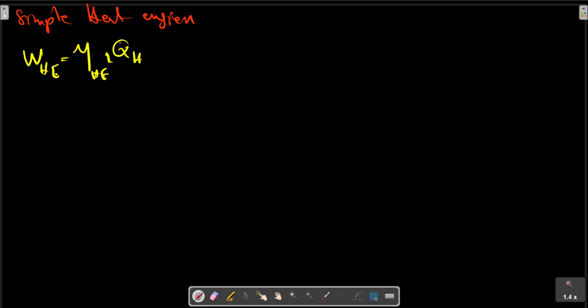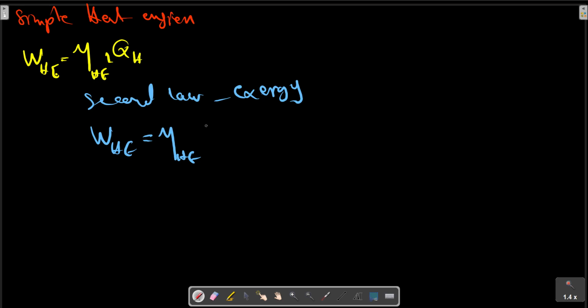What then is the second law efficiency? We basically start from the same relation but express it in terms of exergy rather than energy, and recall that work is 100% exergy. For the second law, we use the exergy relation: W of the heat engine equals eta multiplied by phi_H, which equals eta heat engine times (1 - T0/T), the availability term related to heat transfer.